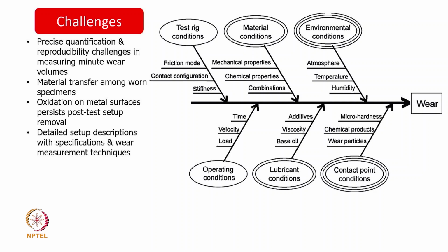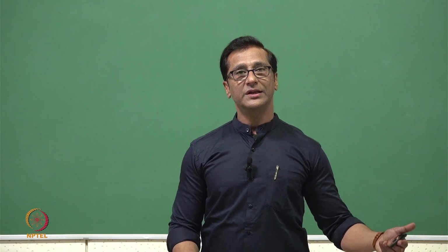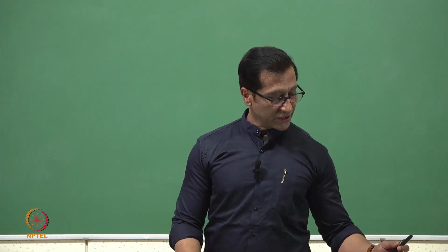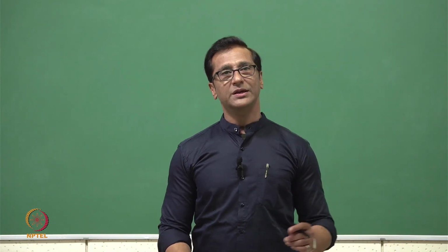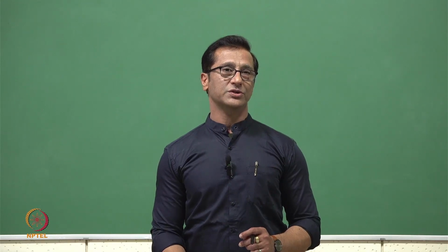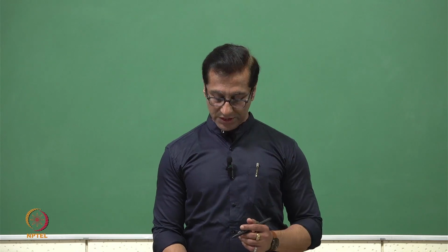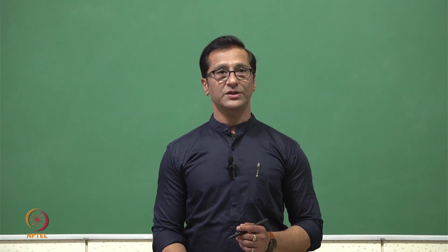Another thing is that many times when we take a surface for SEM and we get a slot the next day or maybe after 4 days, quite possibly there will be an oxide layer on the material. How do we separate that? And how do we really analyze that? That's an important aspect. And then most of the time in literature they don't provide a detailed setup description, and then compiling that information from literature is going to be a major problem for us.